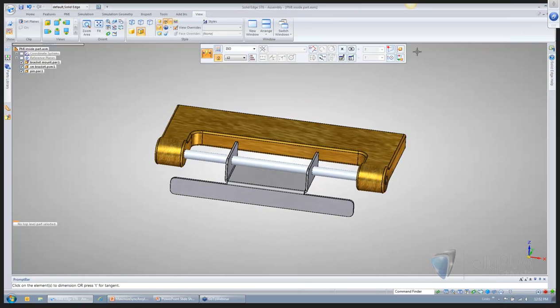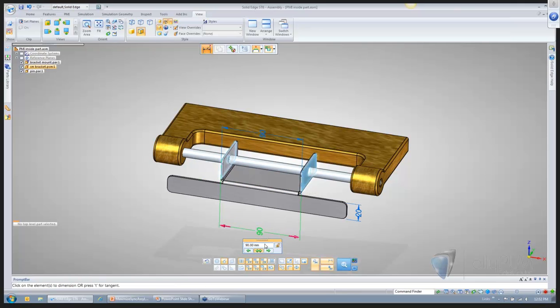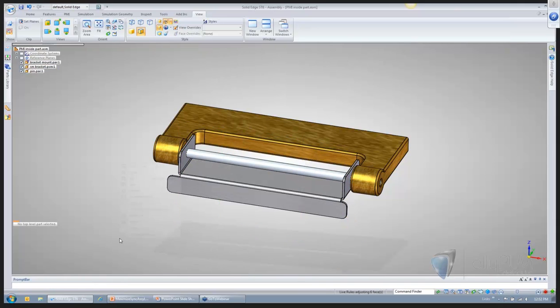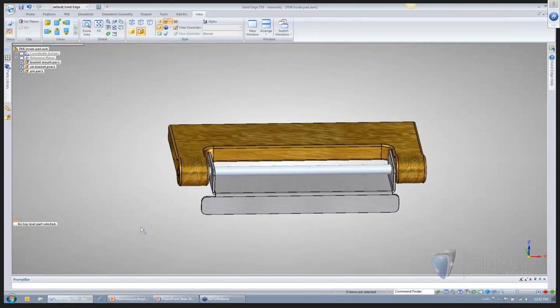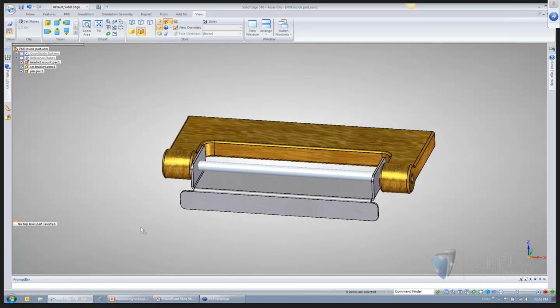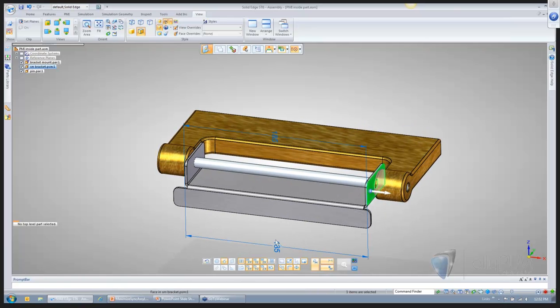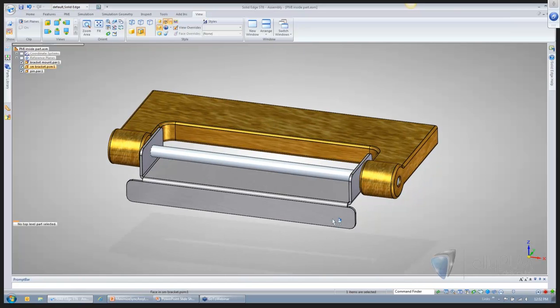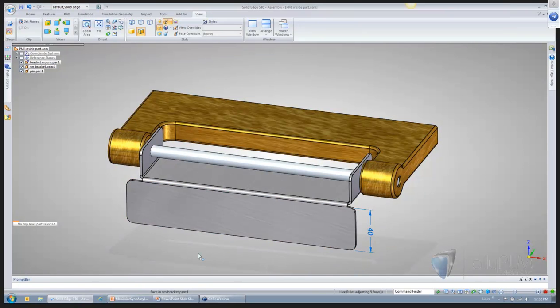So let's do the same thing here. I want to modify this sheet metal component that fits inside here, and I think I set that at 190, so let's just set this guy to 185. And you'll see that we're able to make these part level edits at the assembly and really streamline our thought process and our design approach. And as long as we're in face priority, whenever we select that, we will be re-exposed with the PMI.